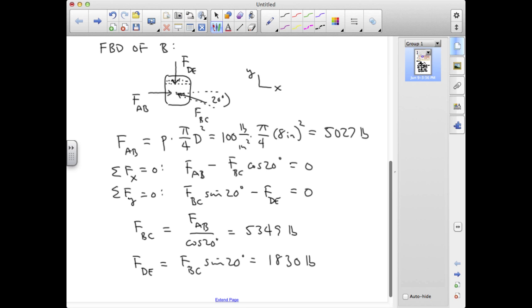Perhaps a more important question is whether we can really use the equations of static equilibrium in this kind of a problem. The motion of a piston, connecting rod, crank-driven system is inherently cyclic, which means the motions of the components in the drive system are far more complicated than just motion in a straight line at constant speed. Perhaps if the locomotive is just starting to move, the accelerations of its components can be deemed sufficiently small to justify the use of static equilibrium equations. Otherwise, we must incorporate principles from rigid body dynamics, but that's a story for another time.